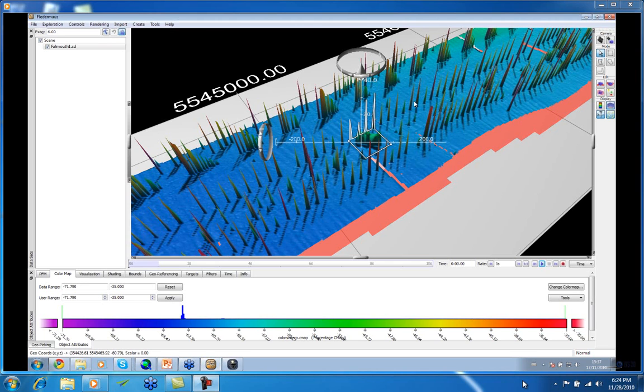What you have to do with Caris is they insist on having their libraries licensed. So you need to have your Caris dongle, if you're using this, installed at the same time as your Fledermaus dongle when you create the PFM. After you create the PFM, you can pull the Caris dongle out and it's not a problem. But when you create or when you unload the PFM, which we'll do later, you need to have that Caris dongle inside. So if you're not seeing the HIPS data path when you go to select HIPS data, it means that your libraries aren't right.